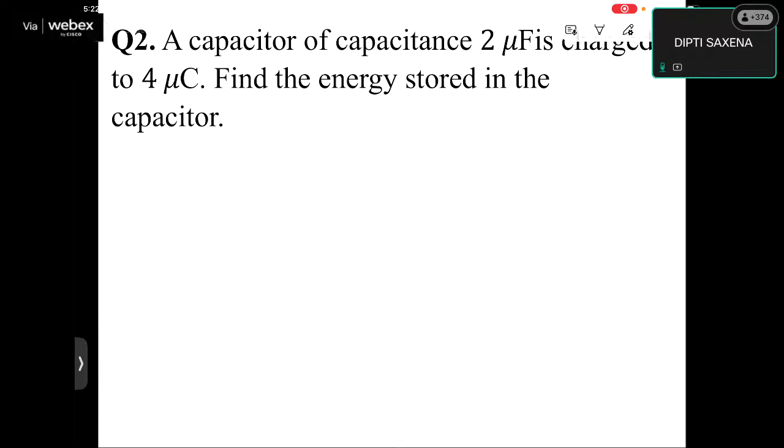You have already seen the resonant frequency is 1 upon the square root of LC. The resonant frequency is not affected by R. The purpose of R is only to damp the oscillations. So you can take just the simple LC circuit. The qubit is realized by a simple LC circuit, but R is always a part of an LC circuit because an inductor is never ideal. Always a loss is associated with it.